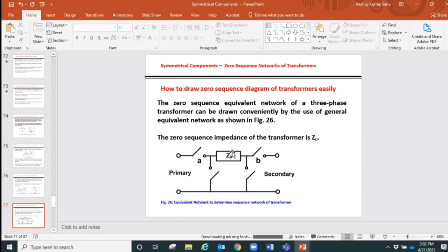We are talking about zero sequence current. So zero sequence impedance is in the picture, not the others. Positive sequence and negative sequence are easy as compared to zero sequence. Zero sequence is much more complicated as compared to the other two. So we show that impedance here. Of course, the other impedance will come from that connecting wire between the neutral point and the ground.